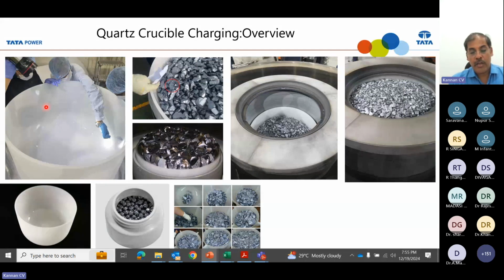Once you put the powder in while loading the polysilicon, after melting, the barium carbonate will make a small wall kind of thing between the silica crucible and the molten silicon, acting as a barrier layer. It will minimize the direct contact of molten silicon with the quartz wall, and also minimize the diffusion of oxygen from the silica crucible into the molten silicon. Right, because oxygen concentration, as I said yesterday, should be as low as possible.